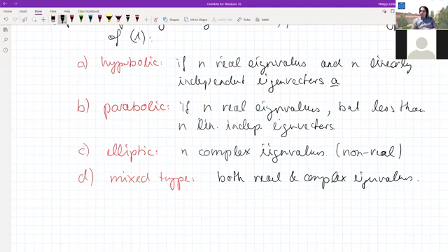And we will see that also when we start to talk about Navier-Stokes, because the Navier-Stokes equations are essentially parabolic equations, but they have aspects of hyperbolic equations when it comes to the convective part, but also the pressure equation, which then will turn out to be a Poisson equation, which is an elliptic problem. So they combine both of these aspects together. So even in the mixed case, it's important to know what the eigenvalues, what the characteristics really are.